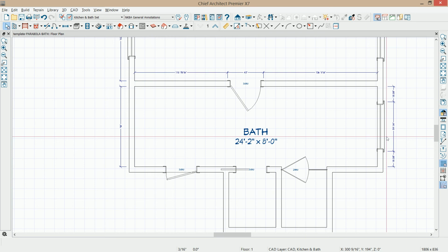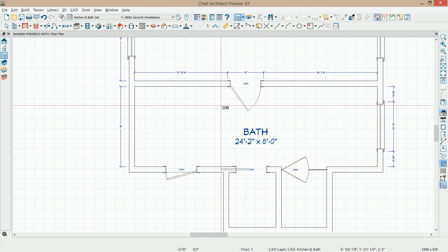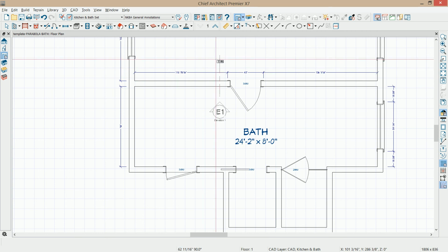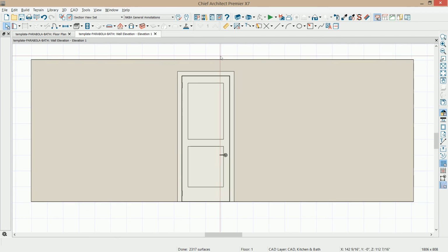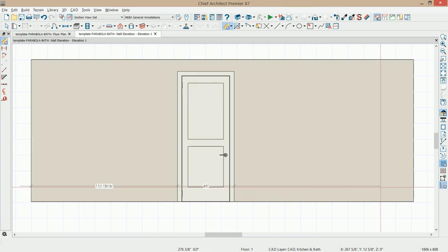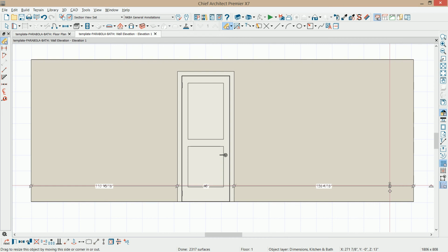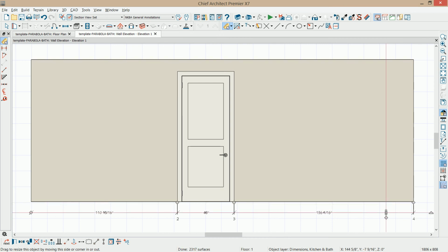One final thing on dimensions, let's go ahead and use our wall elevation. And let's shoot a wall elevation. This is going to be our major sink wall, so I'm going to use our wall elevation tool and take a wall elevation of that. And again, you can use your dimensions simply by coming through here, drawing a line. If I pull that down, you can get your dimensions that way. I'm going to press delete.